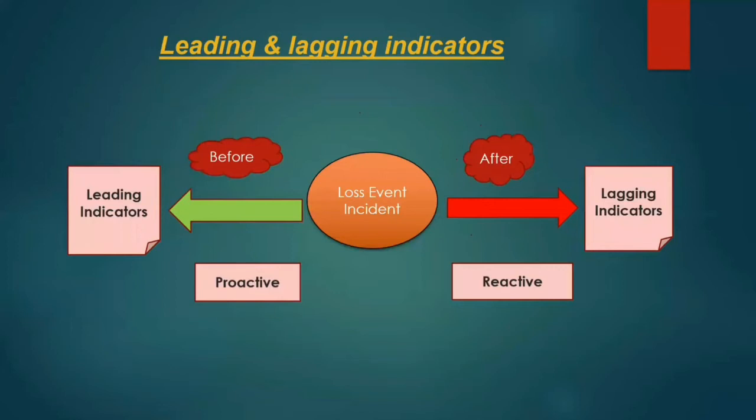Back again to our lessons learned, we found that the next level of management error in the accident was system-related error, which includes, first, negligence of minor MIC leakage or near miss that could lead to death. Look at this figure. This is the event or accident. Before it happens, there are some proactive methods to prevent the event from happening. This is called a leading indicator. And there are also precautions that should be taken to mitigate the consequence. This is called a reactive or lagging indicator.